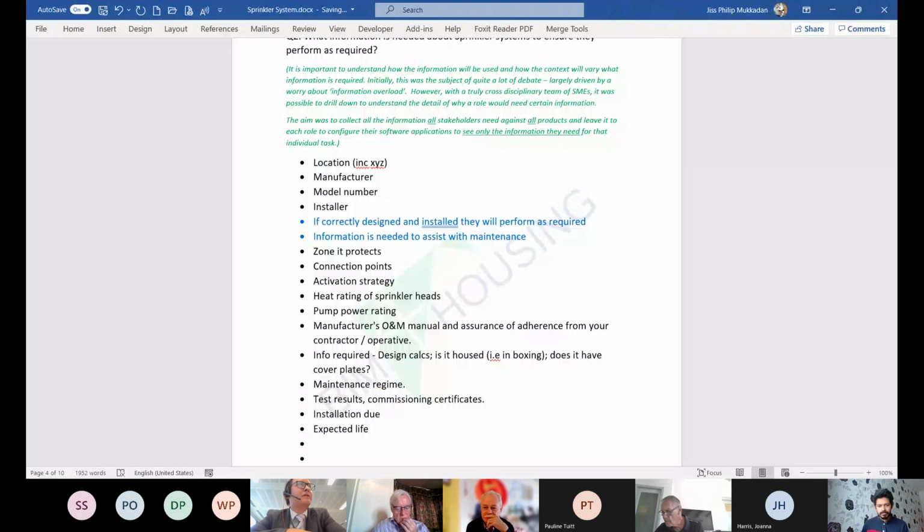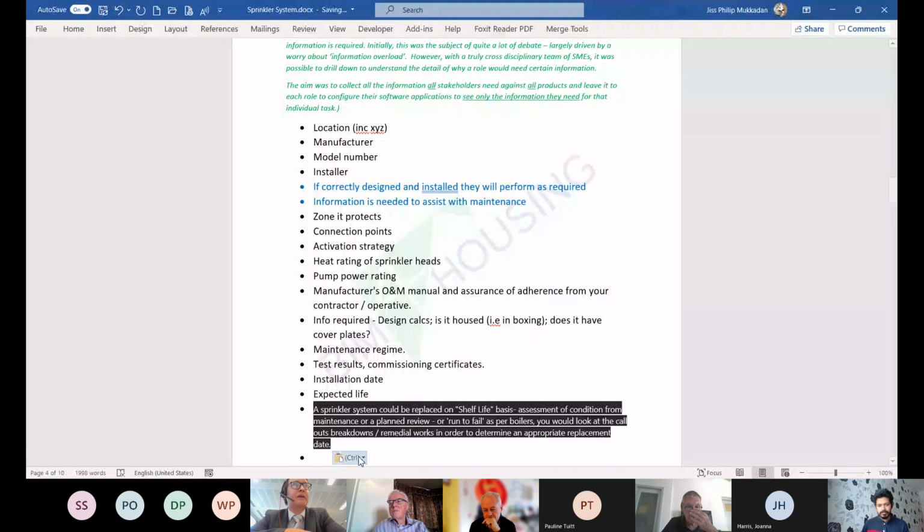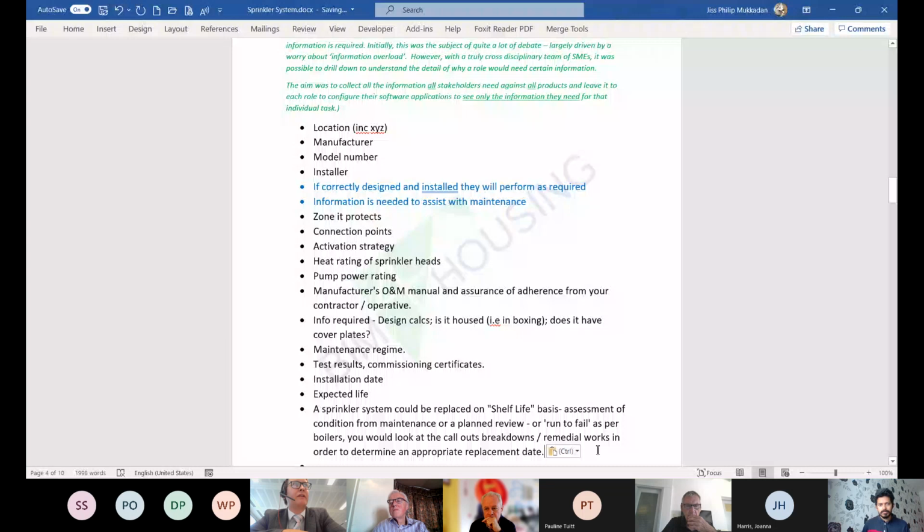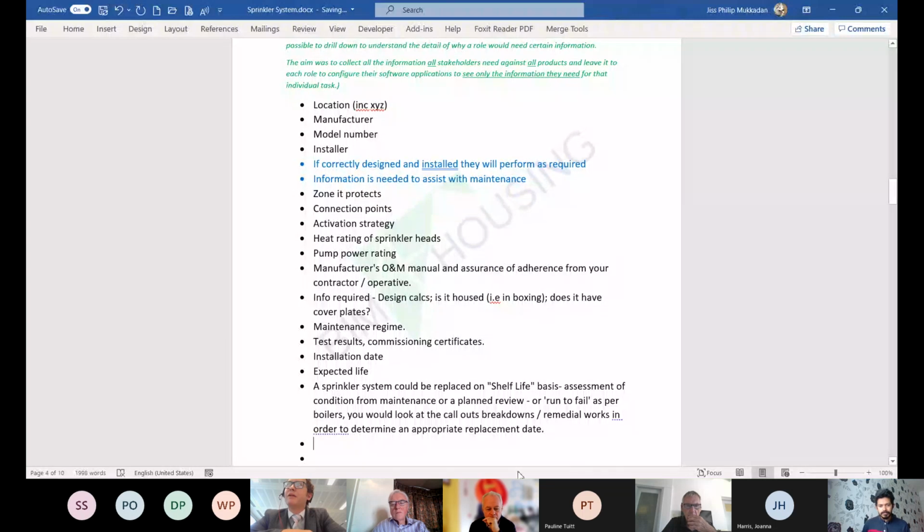Well, I'd say the question came up recently. We were talking in Sibsy about it because we've got some stuff in the guides about life cycle, but I don't think it's actually based on any sort of science. And as you're saying there, Alan, about a 25-year cycle, someone put in the chat about corrosion. I think the more you empty it and fill it up, the more oxygen you get in there, and that's when you get the problems over a shorter lifespan. The less oxygen you get back in there, the more it will be fine. It's like the issue with seam welded galvanized pipe on dry systems. You need to put nitrogen in it, because if you don't, it doesn't last more than about 18 months.